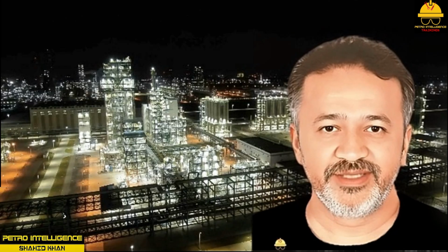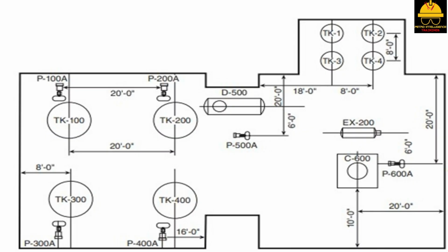Equipment location drawing. Equipment location drawings, plot plans, show the exact location of equipment in relation to the plant's physical boundaries shown in this picture. One of the most difficult concepts to explain to a new process technician is the scope and size of modern chemical processing. Most chemical plants and refineries closely resemble small cities. They have well-defined blocks and areas connected by a highway of piping and equipment. Equipment location drawings provide information about the neighborhood.